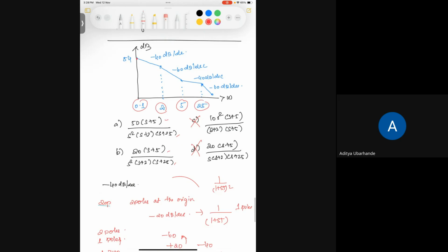So now you look for the cutoff frequency set between 2 to 0.1, it has degraded minus 40 decibels per decade. So that pole we fixed. Okay. Now between corner frequencies 5 to 2, it has degraded minus 20. So one of the poles should be at 2, another pole should be at 5. That is fixed. Then comes the minus 40. Again, one degradation has happened, right? Minus 20. So now how will you judge the gain value here?